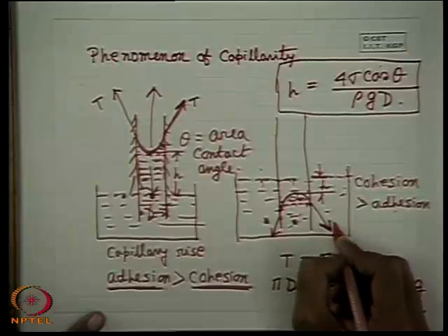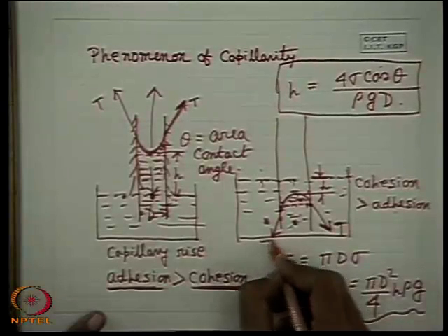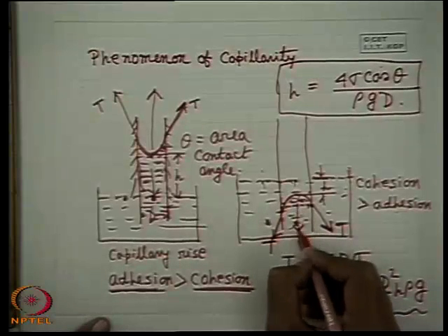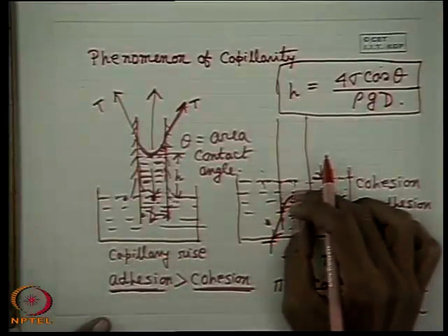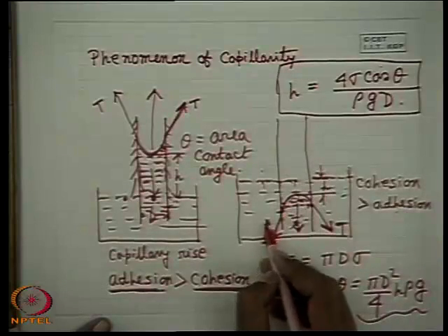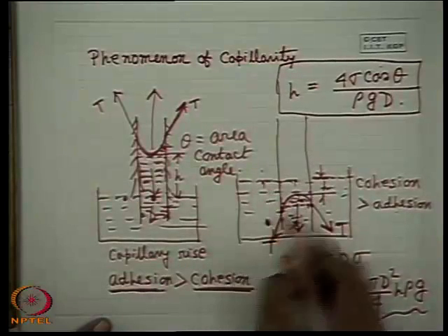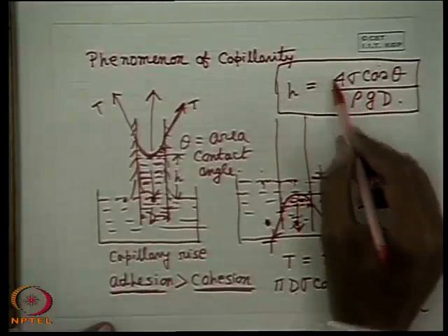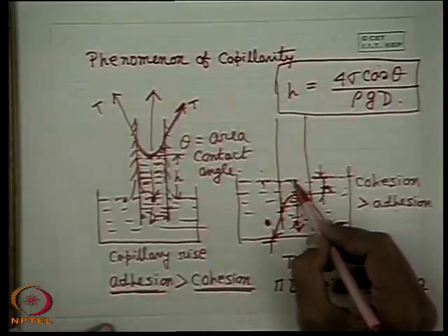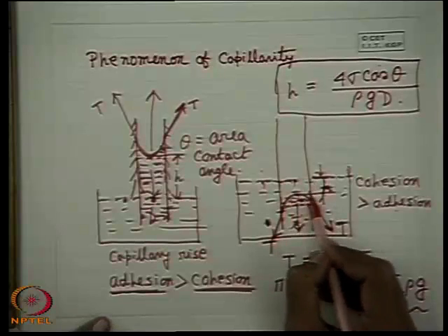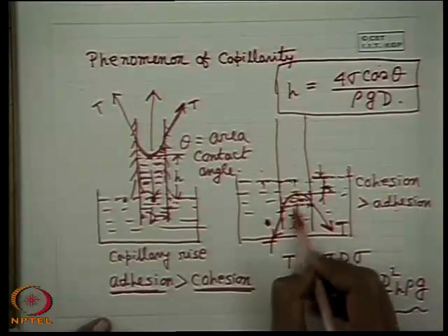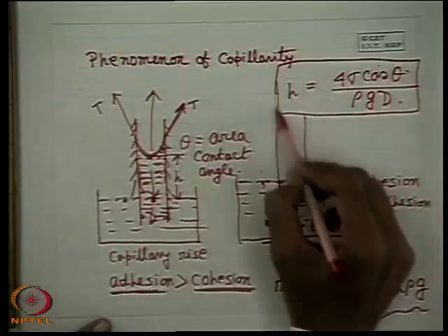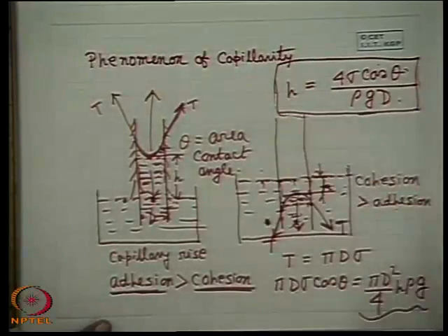So you see the vertical component of this surface tension force acts in this direction, which is added up with the pressure of this less height, and will make the balance of the pressure here. And if this be the h, the difference you can find out is the weight of this column of liquid, which is imaginary. It was not there. If this liquid could have come up to this column, so this weight could have balanced. So from that balance you get the same expression for h.